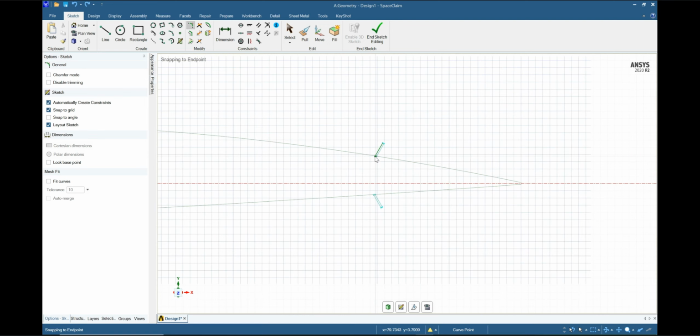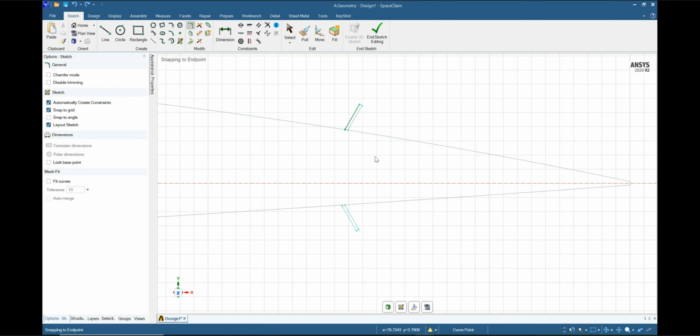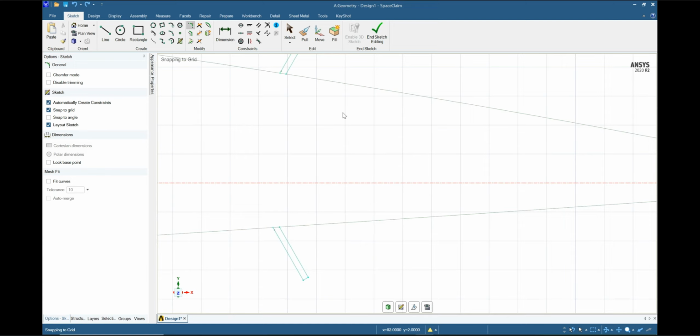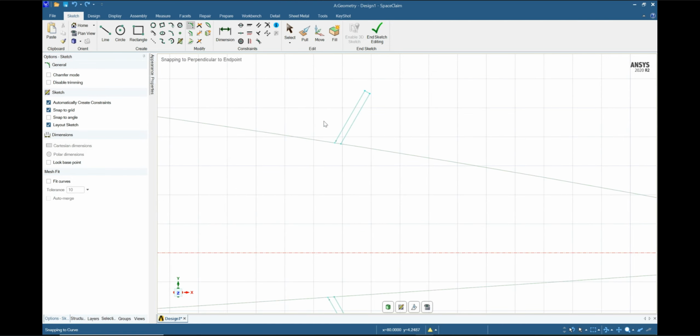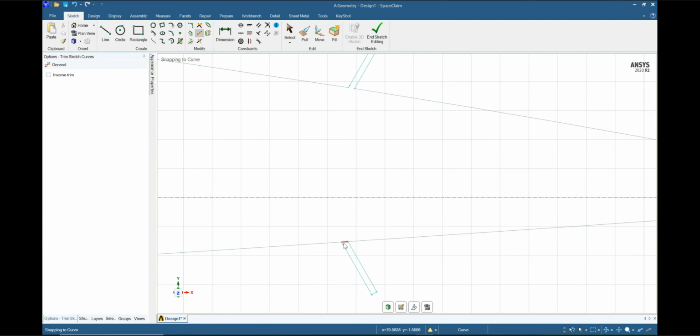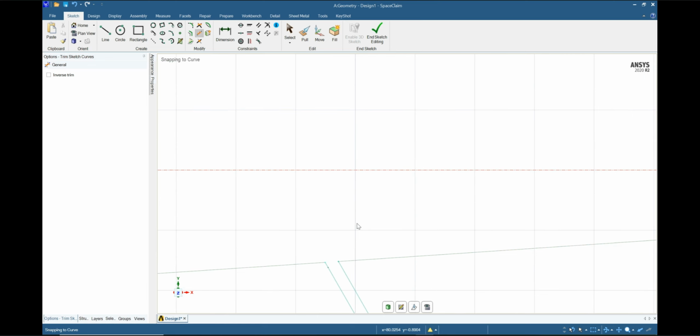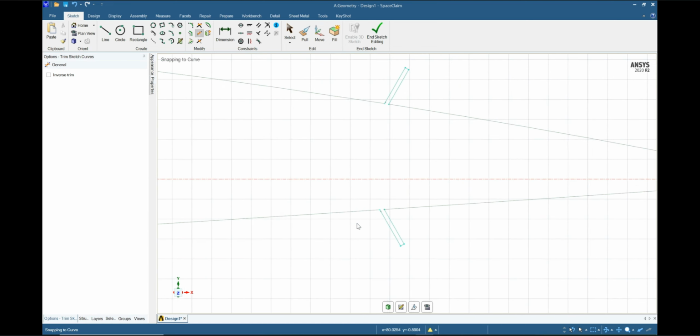As you can see, there is an extra curve at the root of each flap. This segment belongs to the original airfoil and should be removed. Use Trim Away to delete these extra segments so that the airfoil, the flaps, and the cavities form a single continuous curve. Once that's done, you can create a hollow extrusion using the Pull tool.